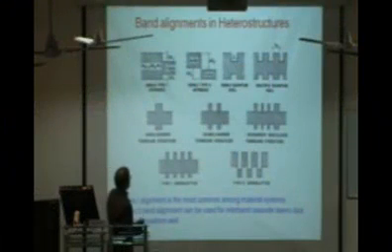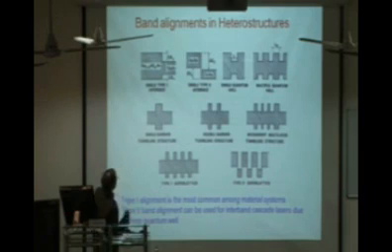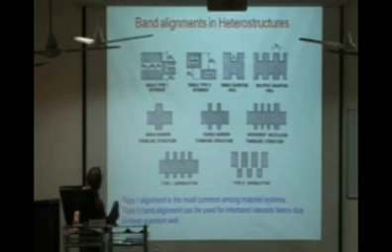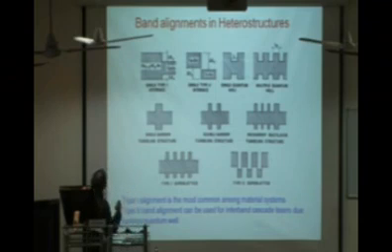Okay, so I'll come to this also. Till now we have seen that if you have one barrier, a high band gap semiconductor and a low band gap semiconductor, we make heterostructures. Heterostructures can be of different types. It can be type 1. In this example, I have taken gallium arsenide, a very common example, as the low band gap semiconductor, and gallium aluminum arsenide of a particular composition as the high band gap semiconductor. They have been chosen because they have the same lattice constant, so one can be grown on another without any defects experimentally. And as you see, we have a conduction band offset and a valence band offset. So our quantum energy states have to be confined within these offsets.